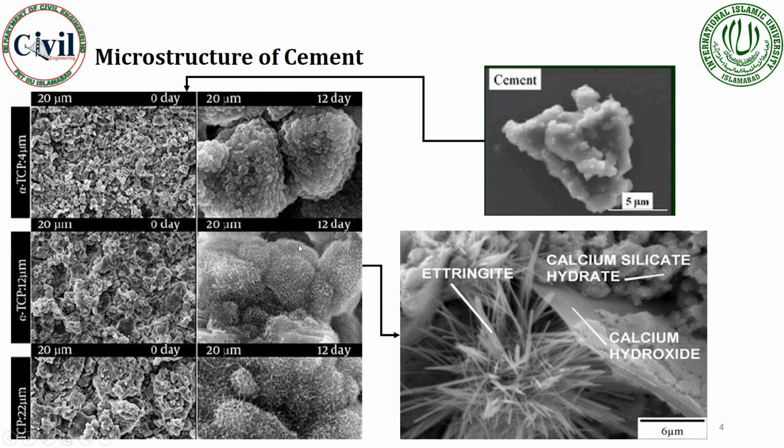Basically, when the cement bag is exposed to some moisture, it gains the moisture and starts hydrating by agglomeration of cement particles among each other to form larger particles. So hydrated or partially hydrated cement represents the lower fineness value. So it is important that before you execute your project, you must check the fineness of the cement so that its quality must be sustained.